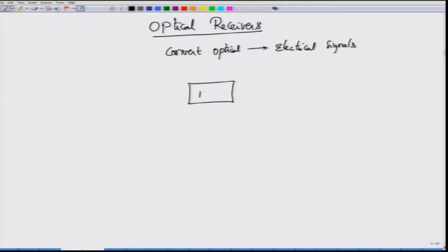This is the photodiode for us; this is just a block diagram at this point. You send in an optical signal, say E of t, where E stands for the electric field, and what you get is an electrical signal which is proportional to mod E of t squared. E of t could be a complex, phasor waveform, and you will be generating the photocurrent, which is time varying, but it would be the magnitude of E of t squared.